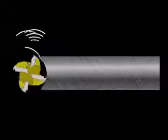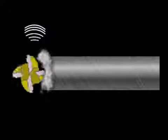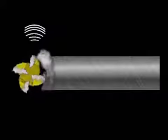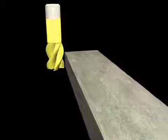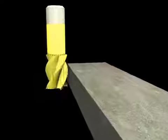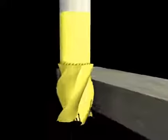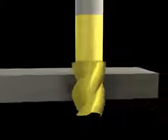If the feed rate is too slow, the tool will rub, increasing friction and producing heat. This can ruin a cutter and work-harden alloy steels. When a cutting tool is engaged into a piece of material, the friction produces heat, which will eventually break down a cutting edge. To reduce heat, consider using coolant, and by setting your speeds and feeds correctly, you will increase tool life, the safety factor, and the quality of your work.